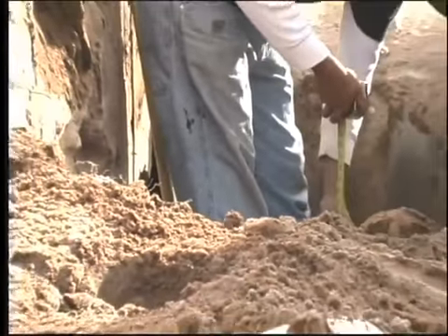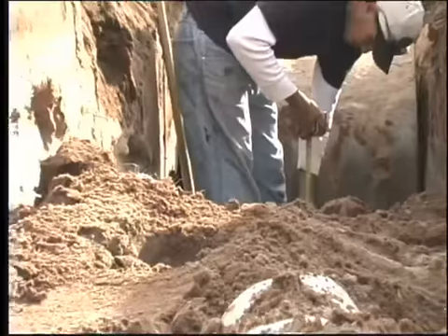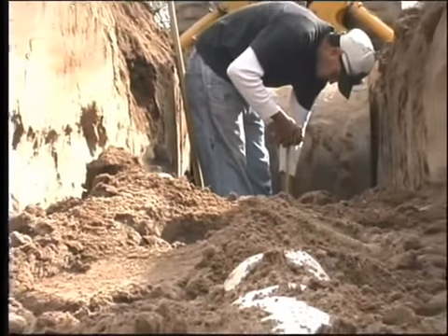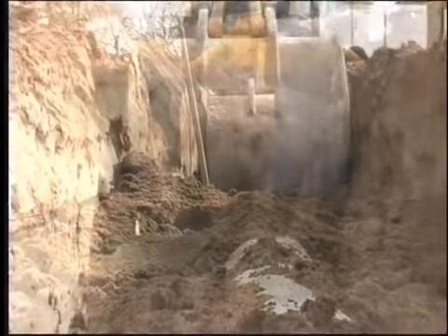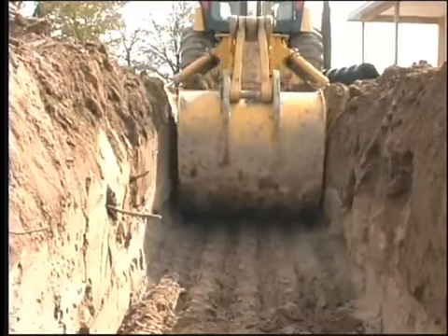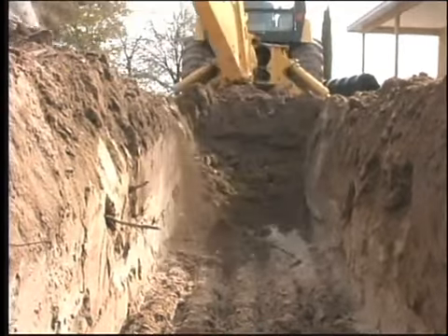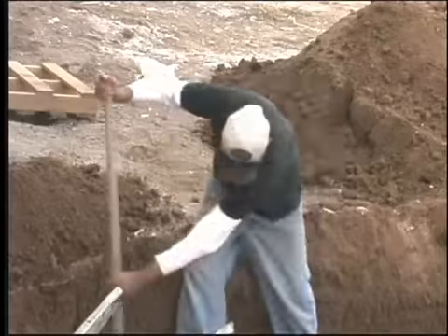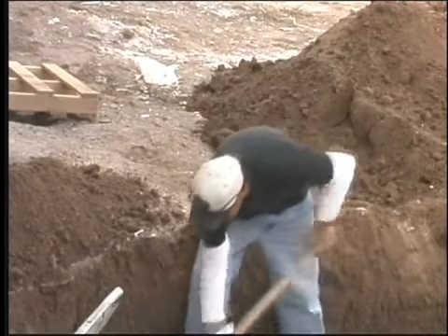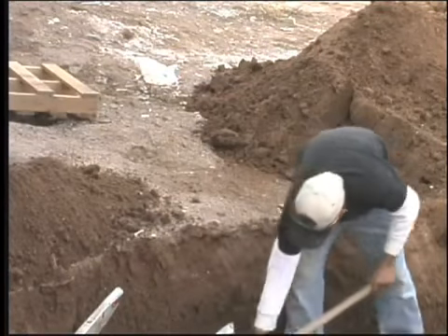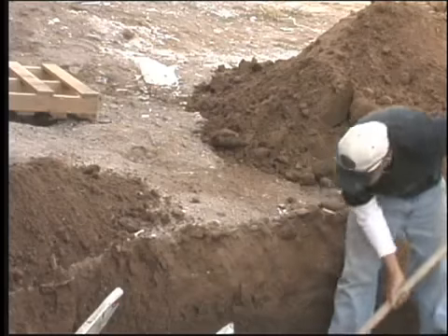Dig your trenches to the required depth and width. Check the bottom elevation as discussed previously to ensure that the trench bottoms are level within local code specification. If the soil on the bottom is mostly clay, use an excavating bucket with teeth to rake each trench bottom to final bottom elevation. Rake to a depth of 1 inch to open up the soil for water seepage. This can be performed by using a garden rake.